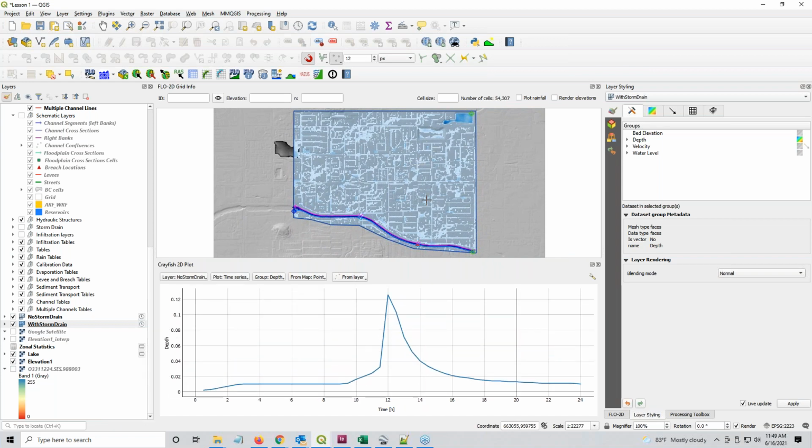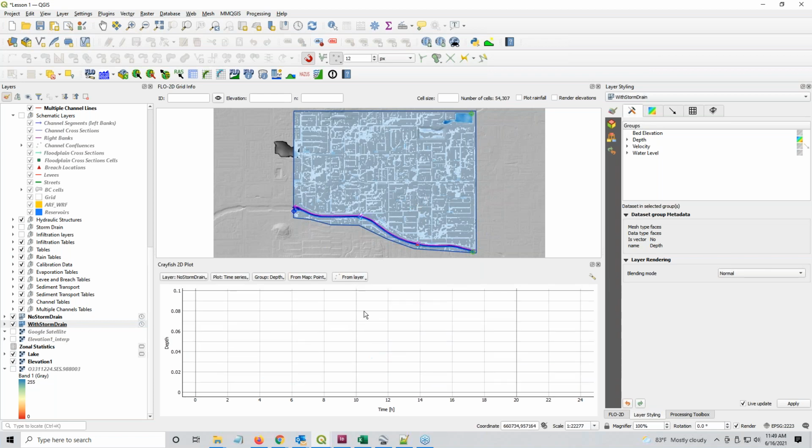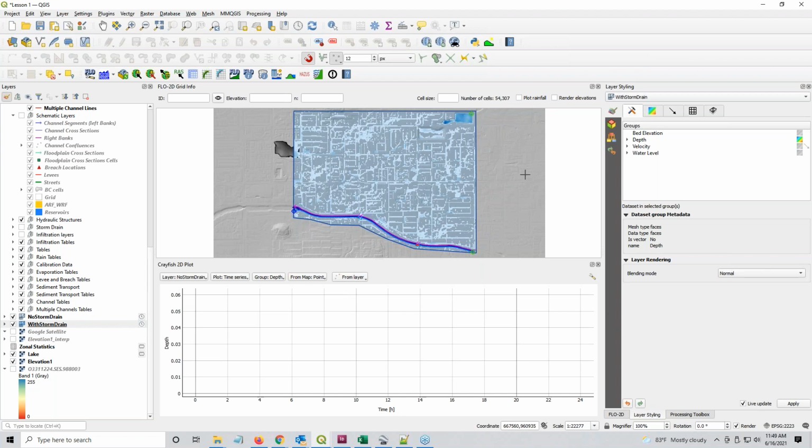Then I can figure out right away why it is not going into the storm drain. Because I can compare this map to what's happening in the EPA SWMM GUI data, because you can plot a lot of things with the SWMM GUI too. Okay, that's basically it for MDAL. I don't have too much else to say about it.